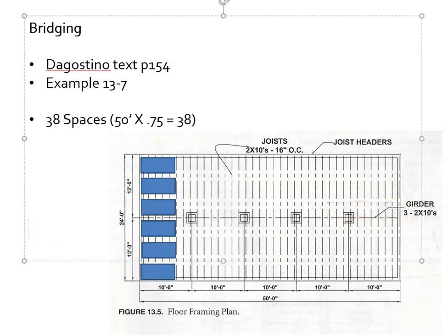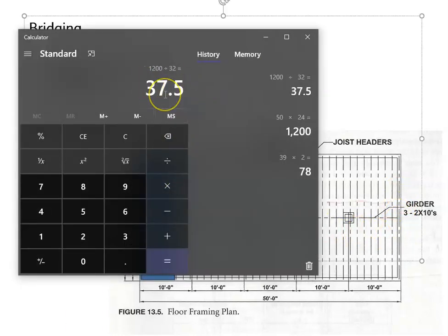But the moral of the story is, if this is 38, I would probably buy, I don't say it would be as much as 10%. It depends on the complexity of the building. A very complex building, I'd say maybe a 10% addition, something like this, I would add 5%, or just a few sheets. So if we're saying 38, let's just clear this and just out of curiosity, if we had 38 sheets and we wanted to figure out what 5% of that is, we multiply it by 0.05, and we'd buy 2 extra sheets. I think that's a good number.